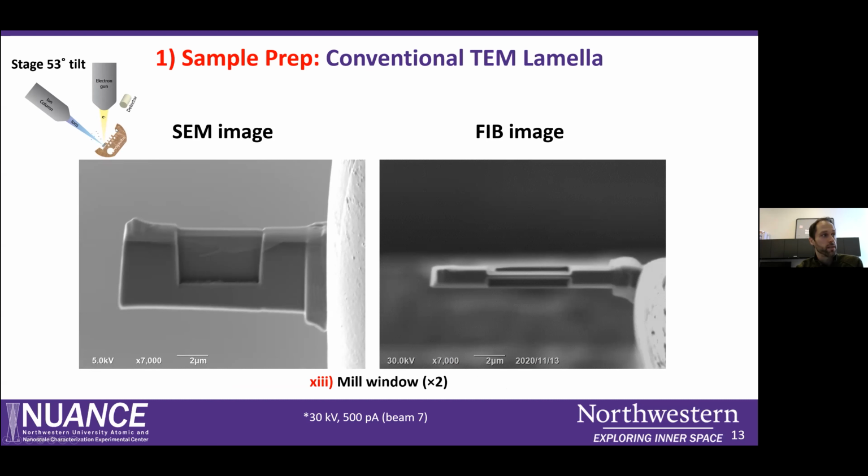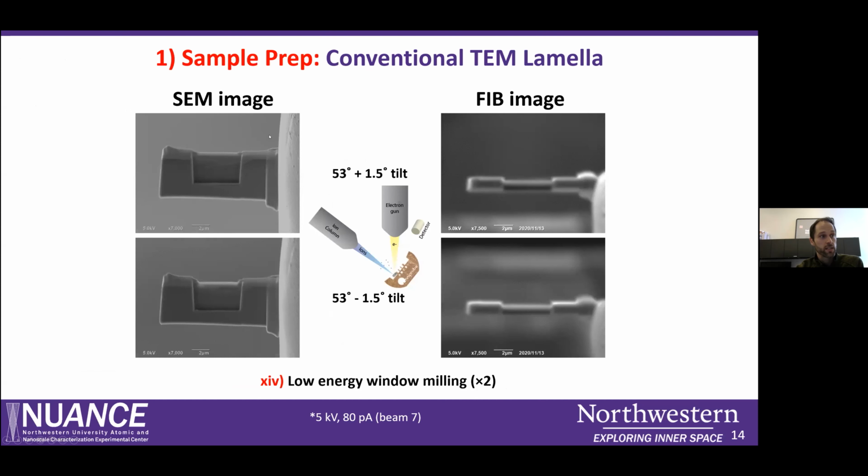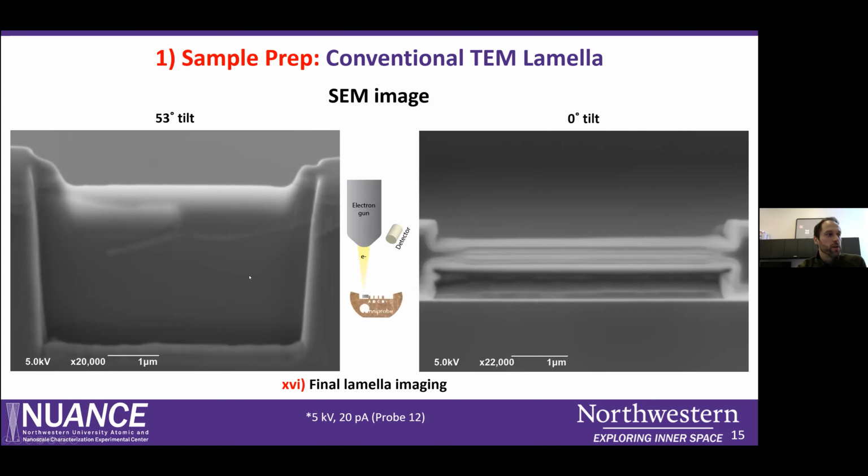So when we're coincident with the ion beam, we can selectively mill a specific region, then use lower energy ion milling to remove material to a smaller degree. So lower energy basically removes less material. And we can end up with a small sample where we have an electron transparent window. So this is the electron transparent window. Typically that indicates, if you see this, that the sample is below 70 nanometers in thickness.